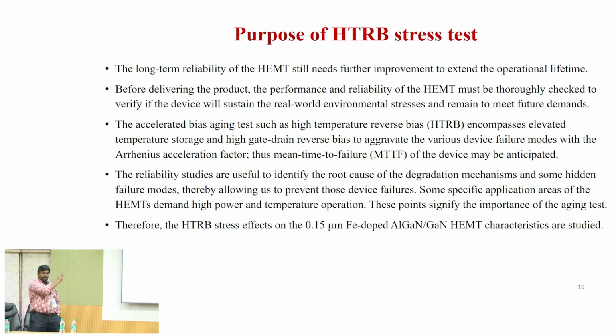Okay, so that's why in industry standard there are some reliability tests. Mostly it is high temperature stress or electrical stress. These high temperature stresses will accelerate your failure rate, so that from the industry standard you can estimate the mean time to failure, but it is a preliminary study towards the prediction of mean time to failure.